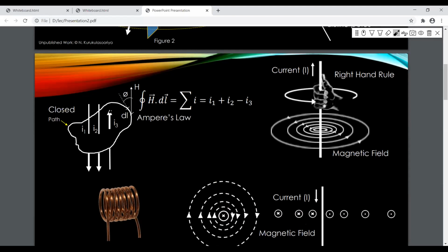And the other thing you should know is Ampere's law. So the basic relationship between the field intensity and the current. What it relates is, for instance, if you consider this closed loop here, we can assume that the magnetic intensity is constant around the loop. So in that case, in order to find the magnetic intensity, you have to know the total current flowing within the loop, right? So I'm only talking about this outer loop, right?